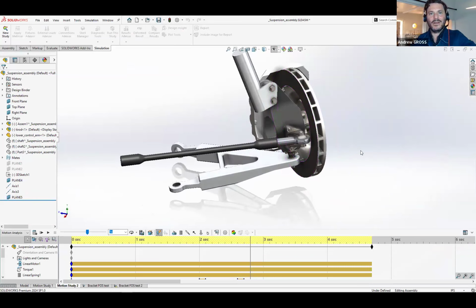It's going to apply about 900 pounds of force going straight up through the wheel. You're like, okay, cool, that's a piece of information. And then you can look at, well, if someone turns a steering wheel at this angular velocity, that's going to apply this much linear force from the steering box onto the tie rod. Okay, well, I can calculate that.